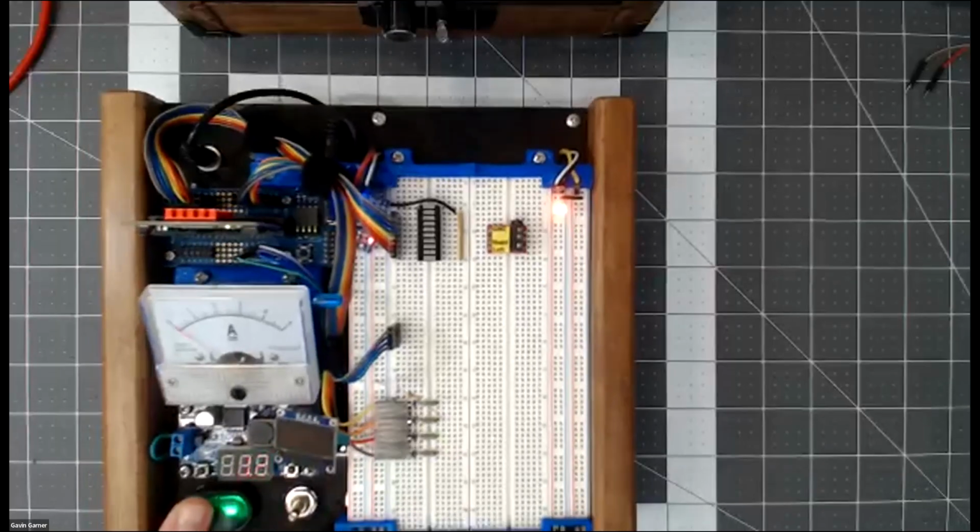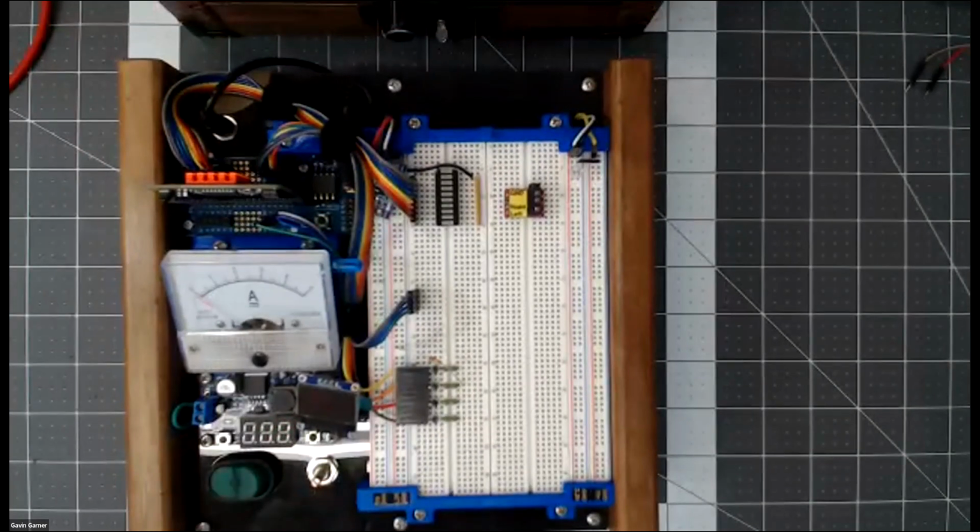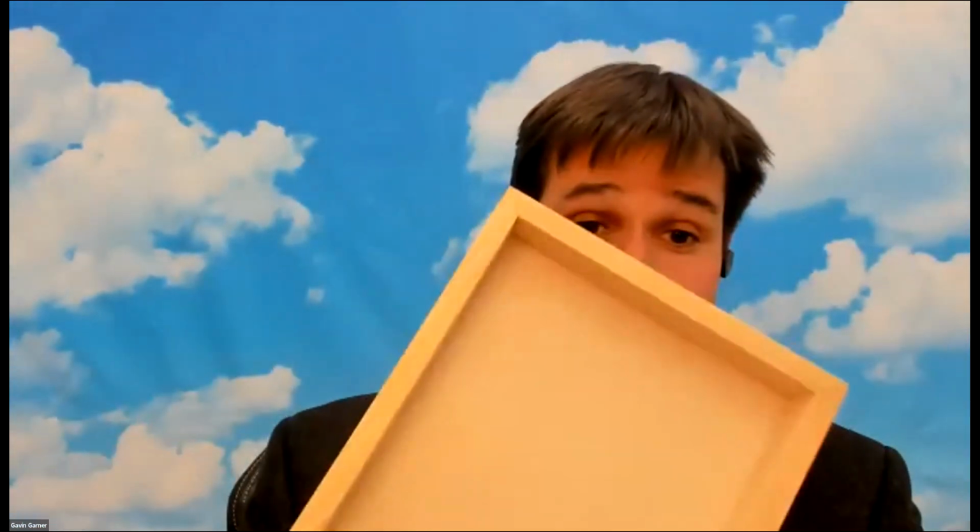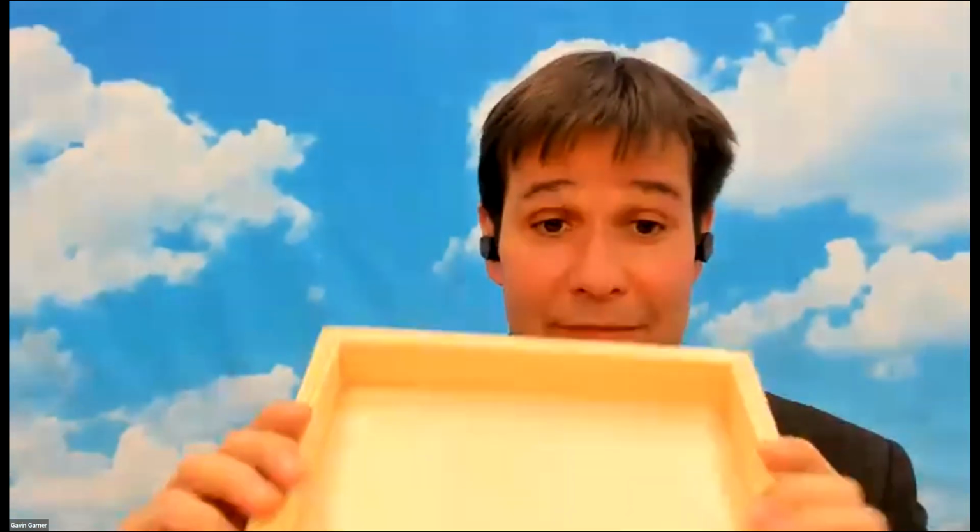Yes, so there are advantages of making things out of wood. I'll switch over to the other video. The major advantage, at least up until recently, is it's pretty cheap. It grows on trees. But another major advantage I found is that it's nice and insulative, whereas another platform I've worked on for many years, where they all shared stations in the lab, was made out of aluminum, and obviously whenever something touched that wasn't supposed to and that was grounded, that was bad. So that's another benefit, is having a nice insulative thing.